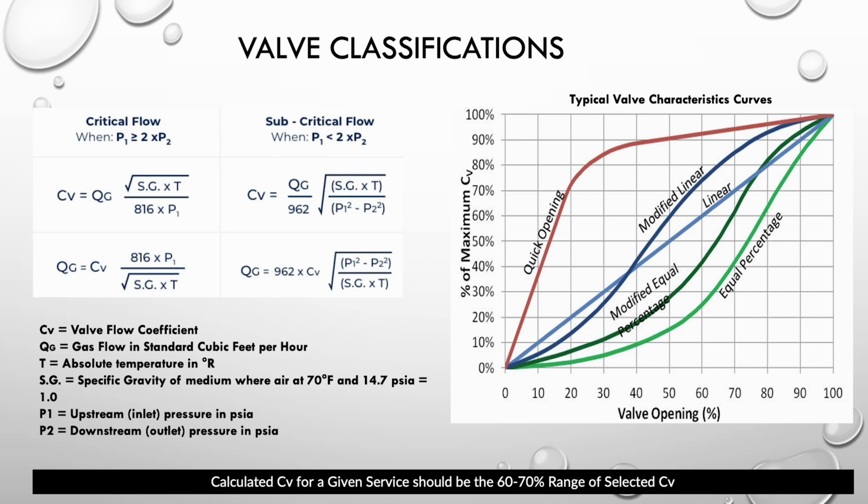Any further reduction of the pressure downstream has zero impact on the flow. Pretty much like your gas phase can't see anything. It's in a state of shock. It can no longer relate to whatever is downstream of it. So that's what sonic or critical flow means.